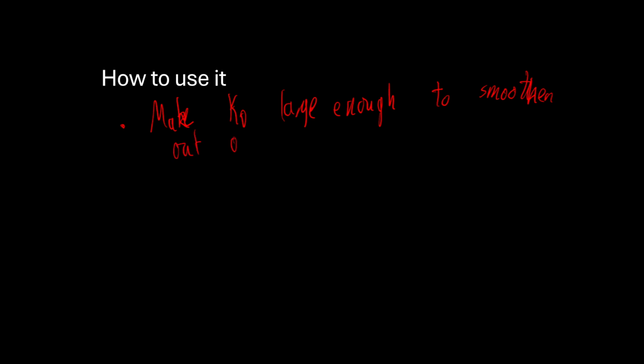How to use it? Make KD large enough to smoothen out oscillations and slow down or dampen overshoot and dampen the system.